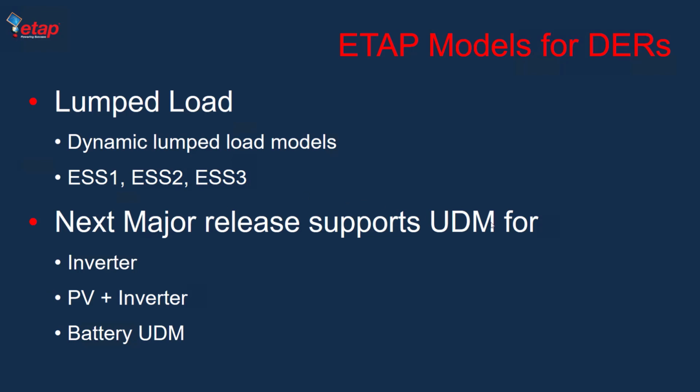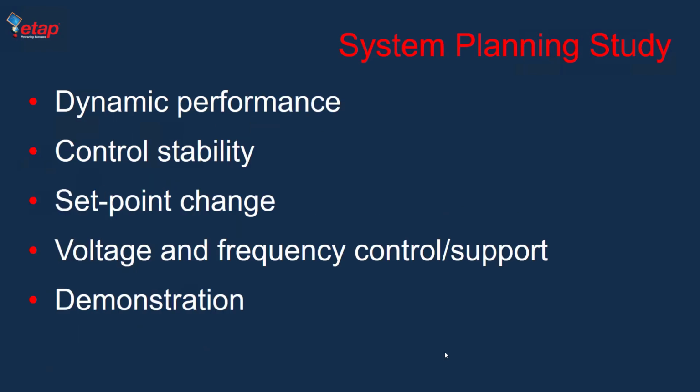In the next major release, we're going to support dedicated UDMs for inverters, PV inverters, and batteries. As you saw, you can still use ETAP 20 to do that, but you need to use either WTG or lump load elements. In the next release, you can use inverter, PV inverter, and battery UDMs independently, without needing a separate element for that purpose.